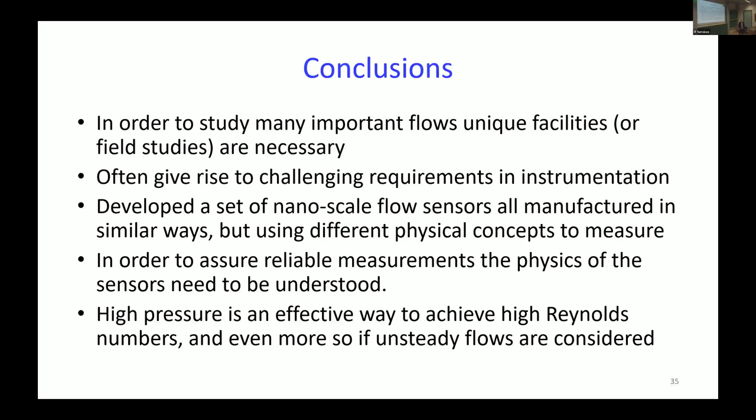Could you estimate that? I mean, Knudsen number, the compression helps you, right? So you're not going into some kind of continuum approximation problem, because you're pressurizing it the same amount as you're actually scaling up. I'm not sure if it's going to be very close to a linear relationship. Actually the opposite might be more of a problem. If you pressurize it too much, the molecules get too close, and you end up with other kinds of forces. But we're in the range where that doesn't happen.